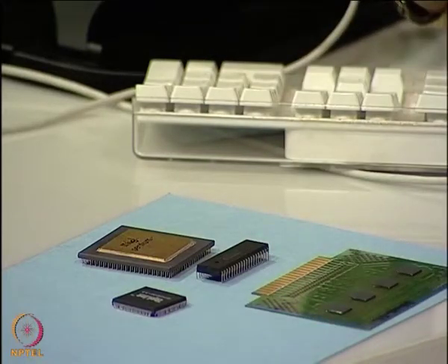From an electrical performance standpoint, leads will create a lot of packaging delays. So, the advantage of using surface mount devices is that short pins or short pin distances from the package body will definitely enhance the electrical performance. We are going to see that.